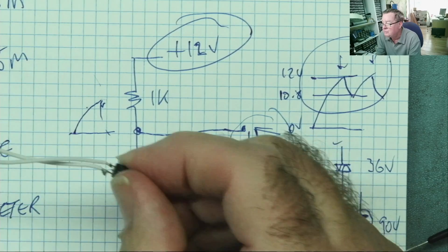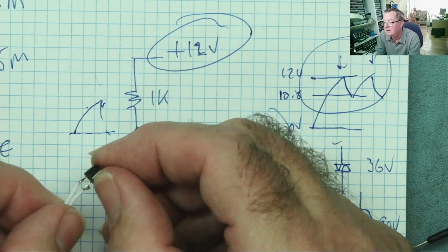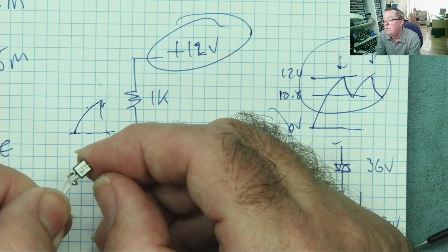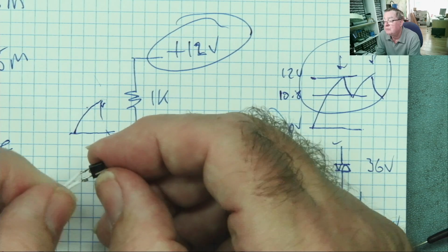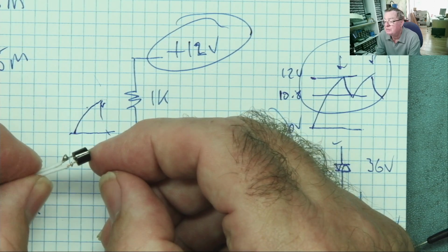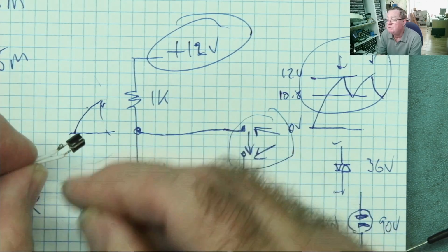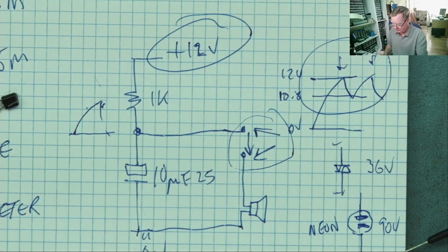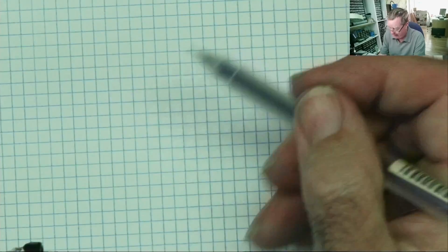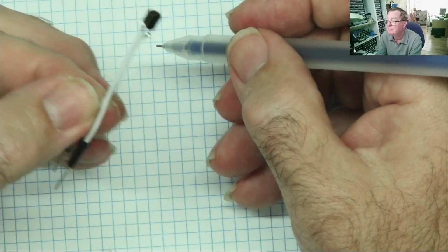Well, actually, it's a transistor. This is a 2N5551 transistor. And if you notice, the middle pin, which is the base, is not connected. I'm only using the emitter collector. With a transistor, you can only do this with NPN transistors, by the way.